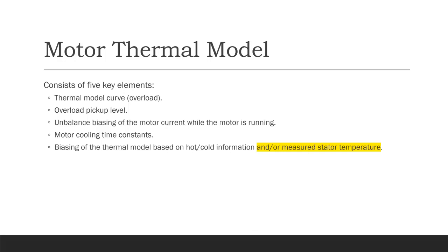We are going to do some future webinars on these other aspects of the motor thermal model. We've already done one on the first key element of this that's stated in this slide, the thermal overload curve that Terry did such a good job with. And we will talk at a later date about things like biasing of the motor because of voltage unbalance, as well as playing around with the motor cooling time constants, and also biasing of the motor based on the hot-cold curves that we obtain from the motor manufacturer.